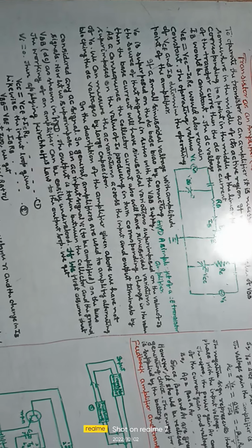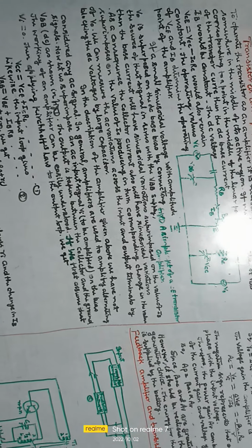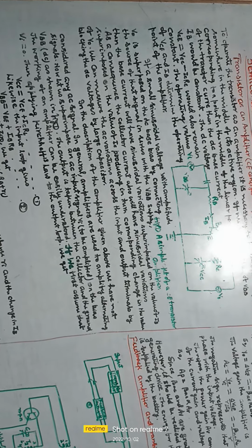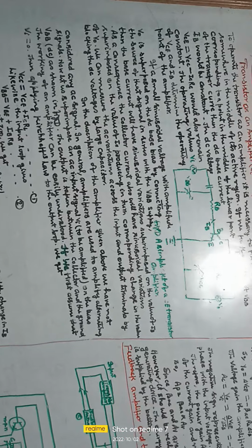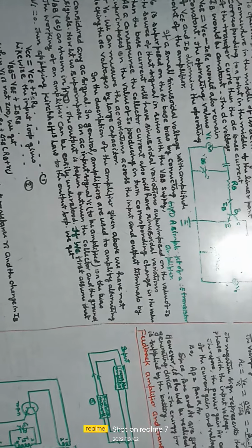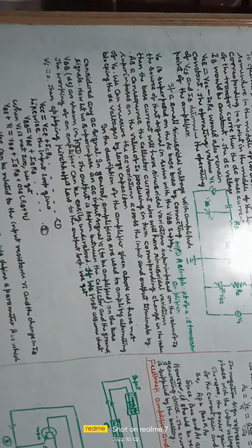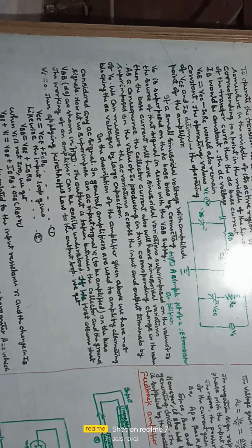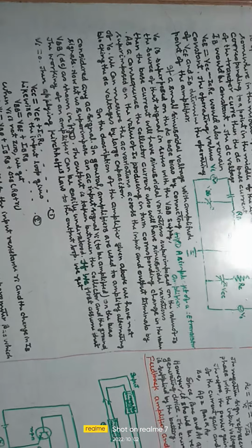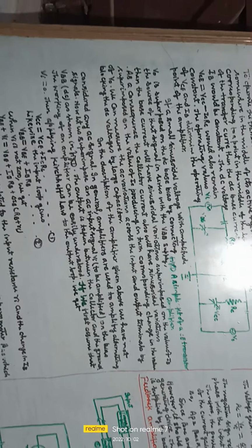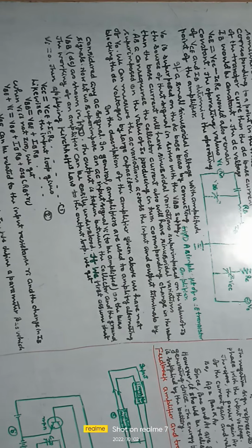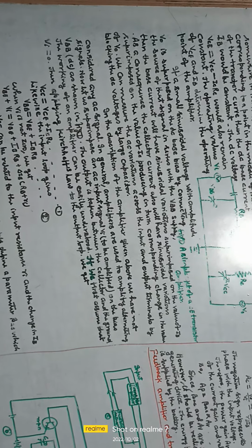In the description of the amplifier given above, we have not considered any AC signal. In general applications, amplifiers are used to amplify alternating signals. Now let us superimpose an AC input signal Vi to be amplified on the bias VBB DC, as shown in figure 1. The output is taken between the collector and the ground. The working of an amplifier can be easily understood if we first assume that Vi is not equal to 0.